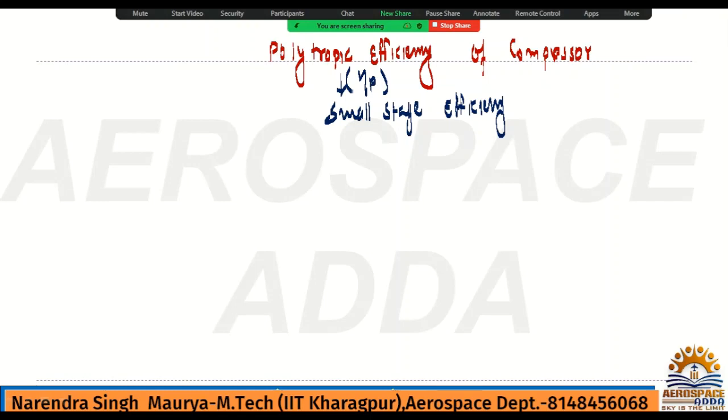In turbomachines you might have derived this during your BTech coursework. This was the derivation for 8 marks if you remember: the sum of isentropic temperature rises for all the elemental stages is always greater than the single overall isentropic temperature rise. We are not going to derive that part. I just want to give the relation between the polytropic efficiency and isentropic efficiency, which is very important. The word small stage is what helps you understand the small stage efficiency or polytropic efficiency of a compressor.